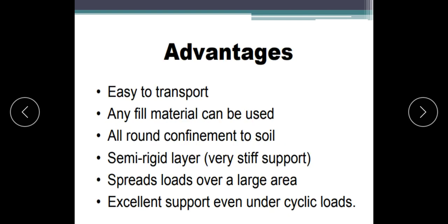The advantage of this is that it is easy to transport. Any fill material can be used, like aggregate or soil or small boulders. Then there is all around confinement, so it provides 3D confinement. It is a semi-rigid layer, a very stiff support that spreads load over the area, and it is also a very good support even under cyclic load.